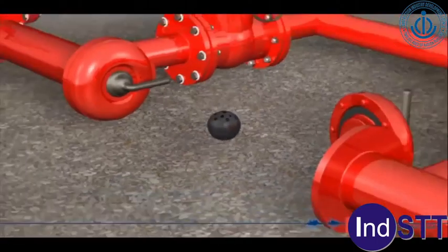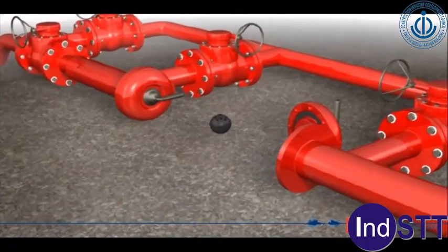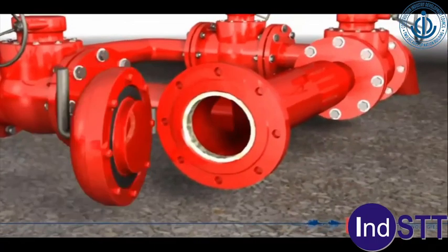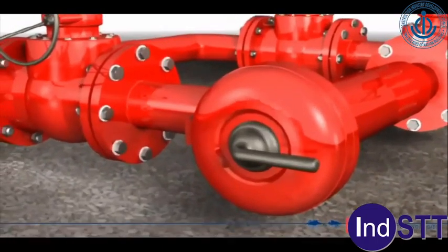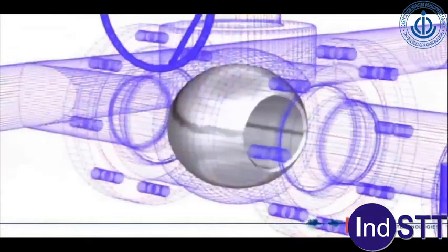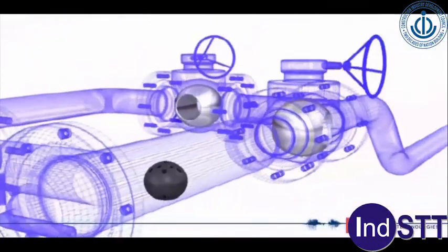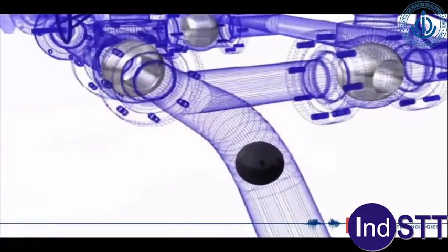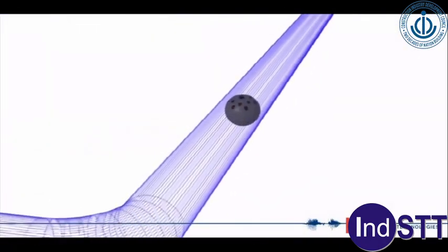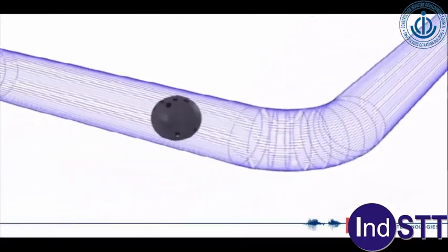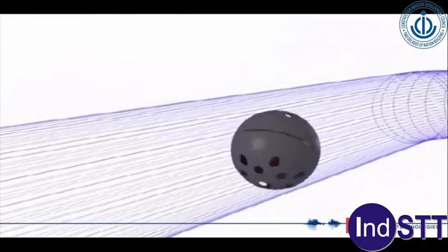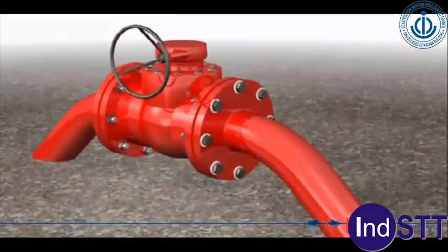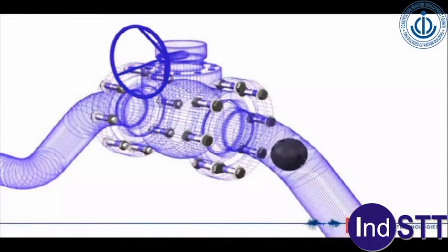The Smart Ball inspection tool can be easily deployed and retrieved using existing pigging facilities. In non-piggable lines, the tool can be launched using standard off-the-shelf fittings. Once inside the pipeline, Smart Ball easily rolls along the bottom of the pipe as it is propelled by the product flow. Since Smart Ball isn't a full-bore tool, it can easily navigate any bends within the line. Smart Ball can be tracked using surface mount sensors, typically placed on block or check valves, as well as using above-ground markers placed at selected surveyed points.